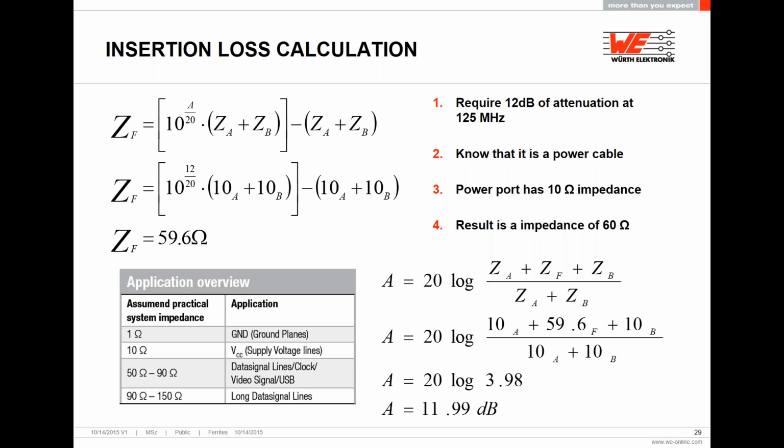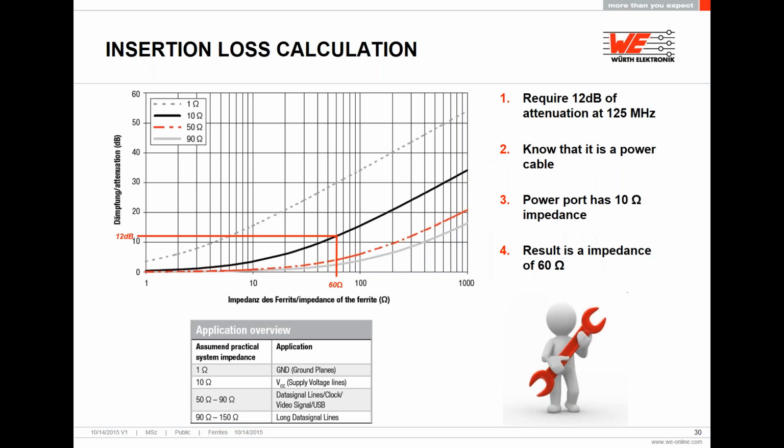So pretty much what we did is that first we just calculated the impedance needed for the attenuation that we need, and then we just confirmed that this impedance value is actually correct. So if you have the same scenario, but this time you use a nomogram, you will find that you quickly come to the same conclusion without doing any mathematical equation. Keep in mind that the frequency is built into the impedance, and therefore you do not have to use the frequency when using a nomogram.